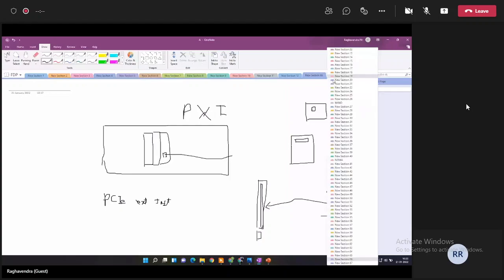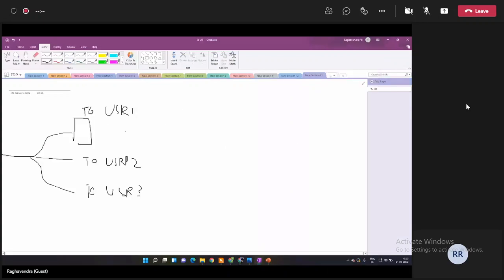So, coming back to this, let's say I'm using multiple USRPs. You can define that these three are happening in parallel in your software itself. But like I said, your CPU resources, your applications that are running on your desktop, are always fighting for CPU resources. So usually what happens when I say parallelism is that in a very quick fashion, it will implement this, then this, and then this. Now, there is a very good chance that right after it implements turn on USRP1, some Windows service could take access to the CPU, delay it for some amount of time, and only after that USRP2 is turned on.